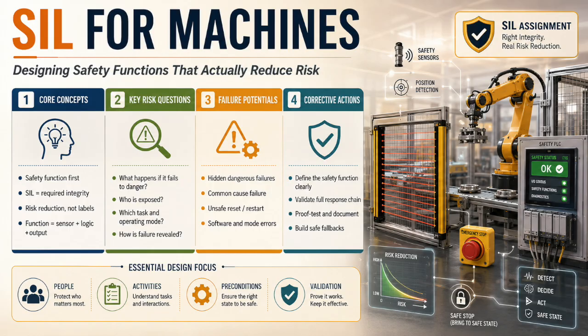Who can select the mode? How is the mode indicated? Can the mode be changed unintentionally? Does the selected mode enforce the required safety limits? Does leaving the mode restore normal safeguarding? Can the machine restart unexpectedly after mode change? Does reduced speed also control force, direction, and stopping distance? These questions are not details, they are safety.